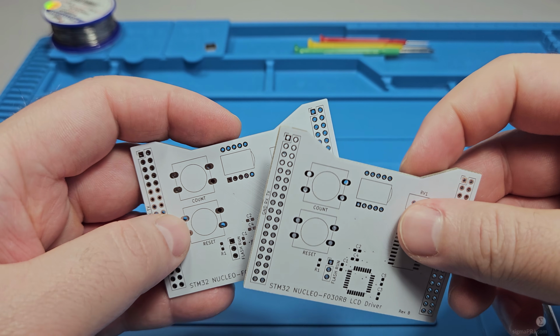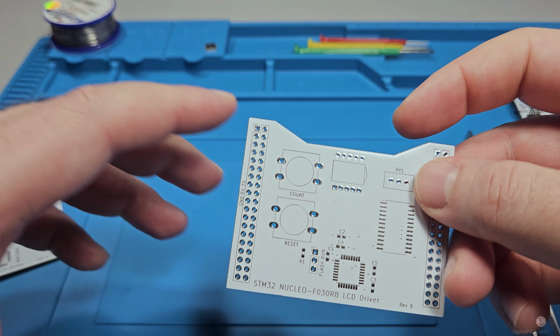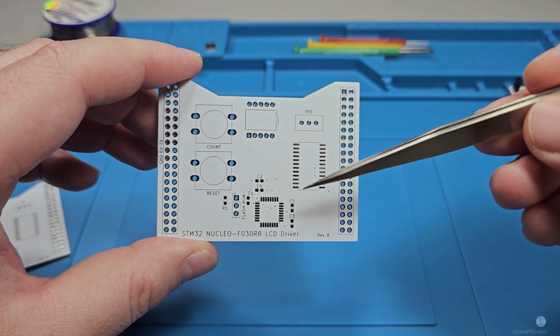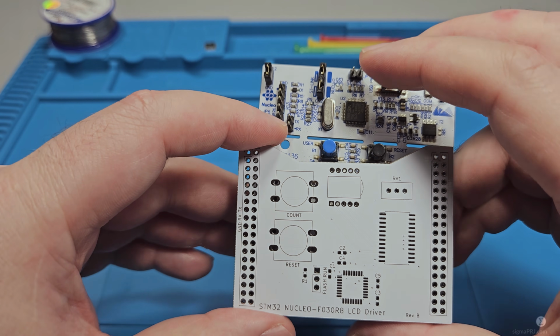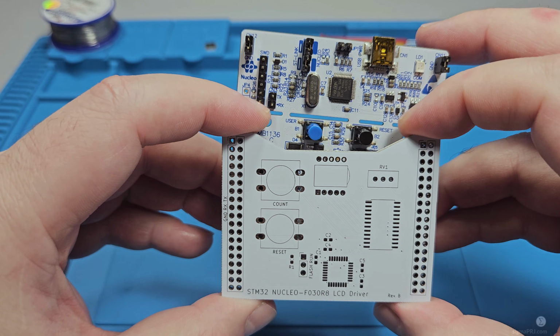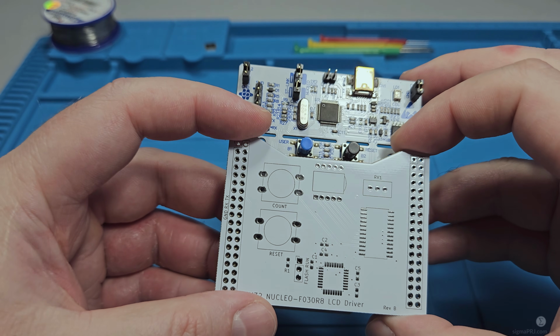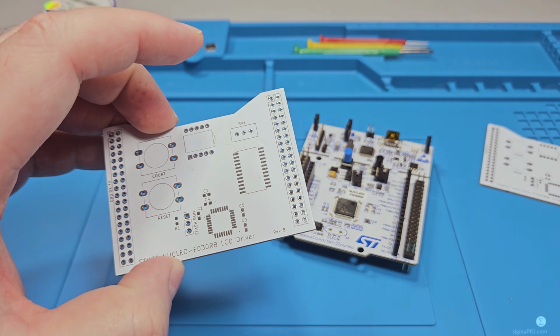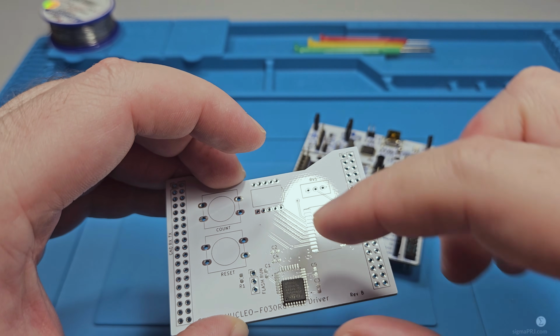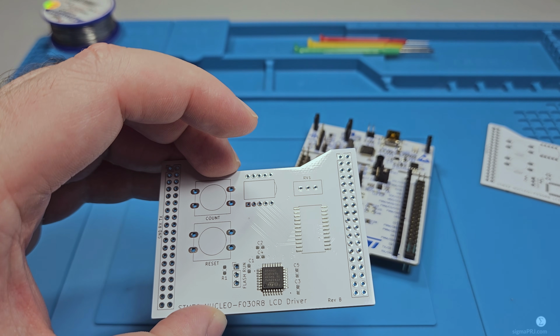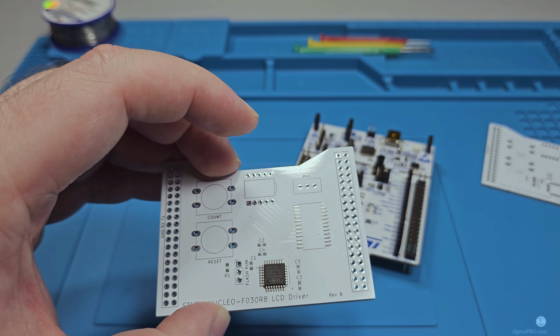One will have all LCD components and connectors populated, except STM32 microcontroller itself. This way we can plug it into Nucleo board, and we can debug everything using Nucleo STM32 chip. Another PCB will have all components populated, including STM microcontroller, so here we could drive our LCD independently from Nucleo